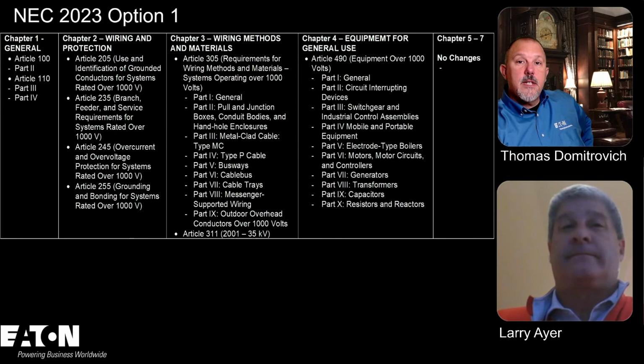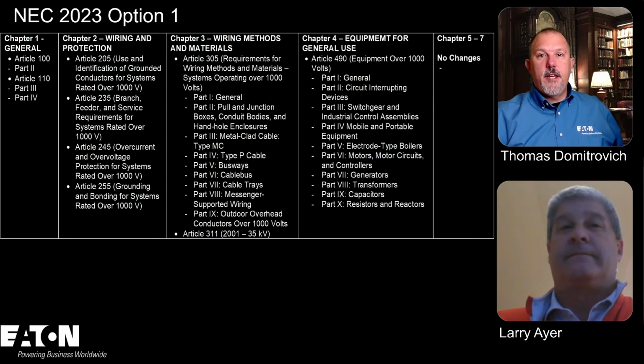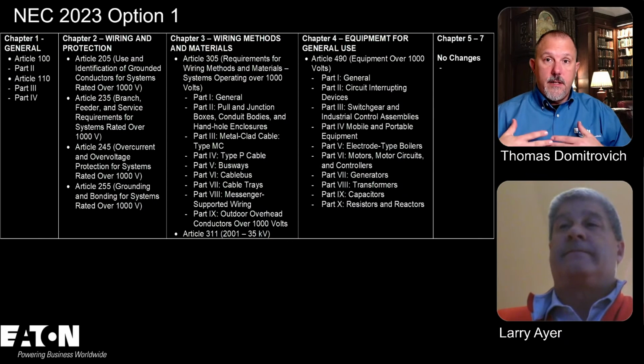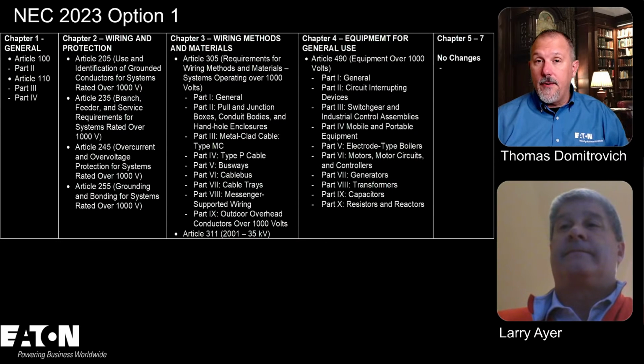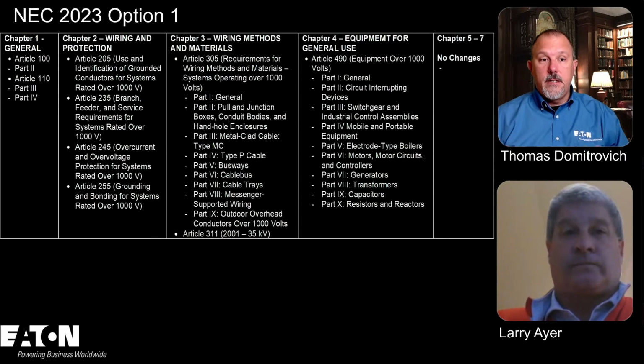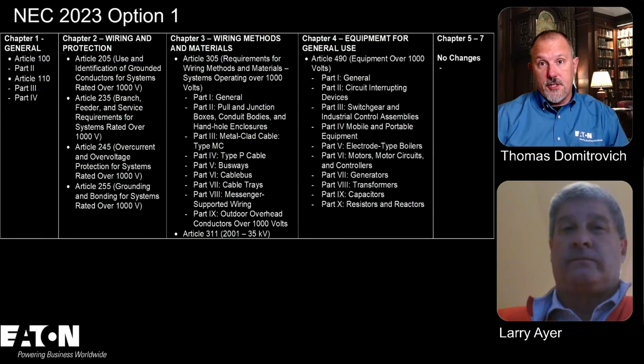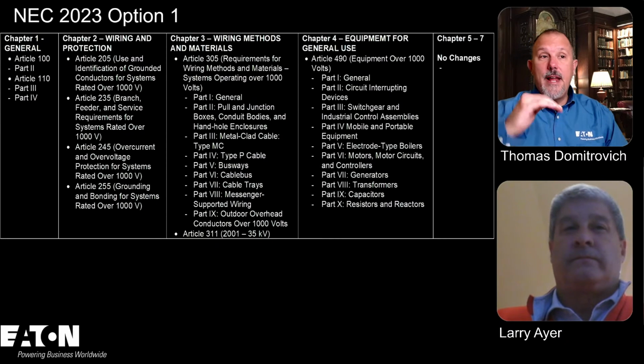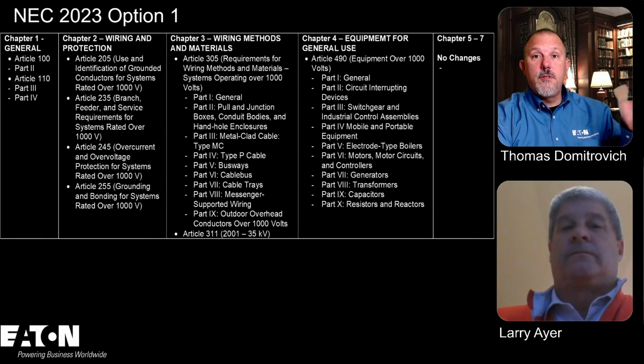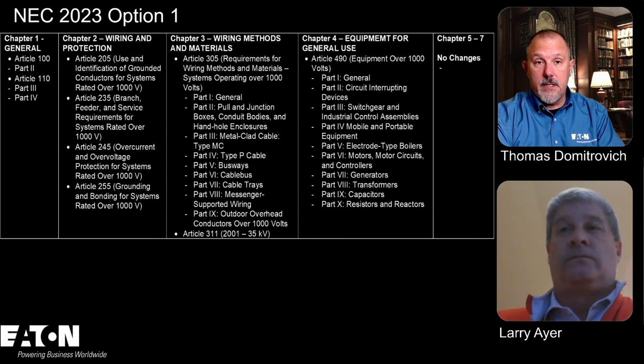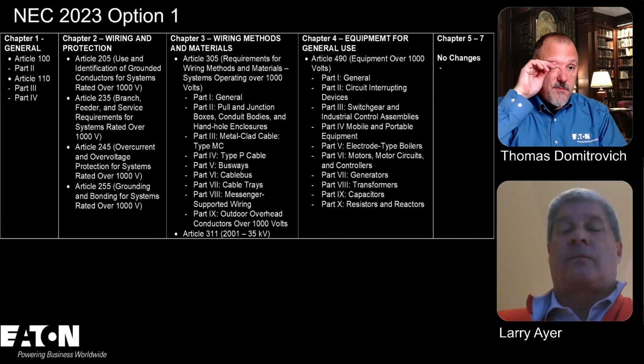Yeah. Now I think some would argue that that line of demarcation between the utility and the owner is sometimes a gray area, and debated and discussed from application to application, which presents different types of configurations. But the National Electrical Code doesn't apply on the utility side. They use the NESC, obviously. So that's why that line in the sand, so to speak, is really critical and important for inspectors and for designers and contractors. Correct. Yes.